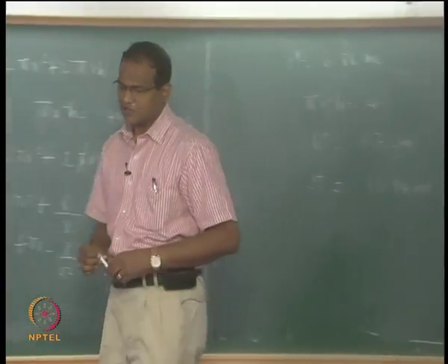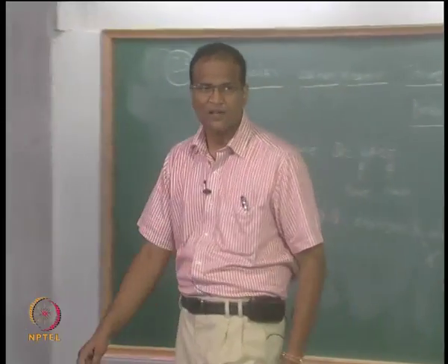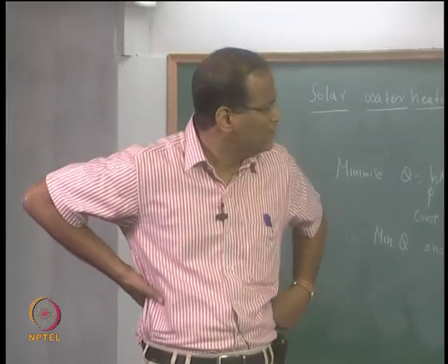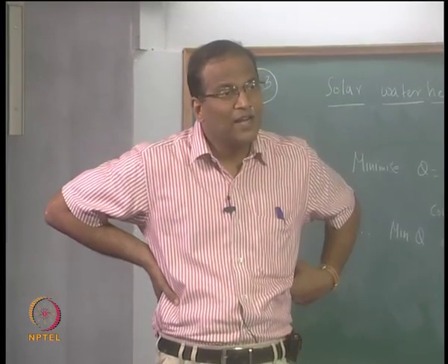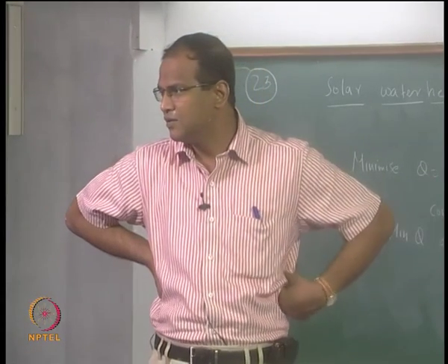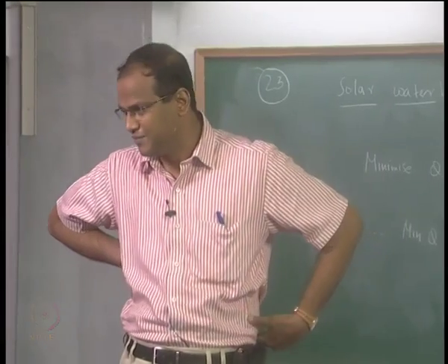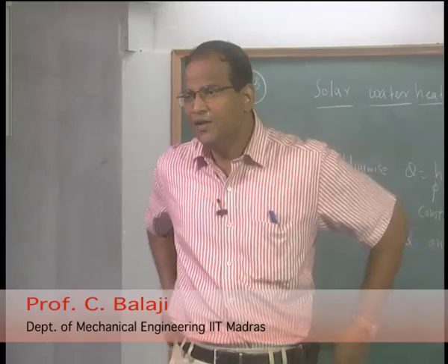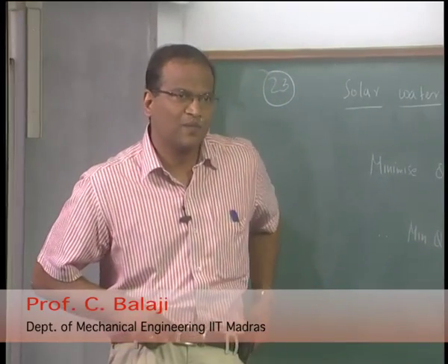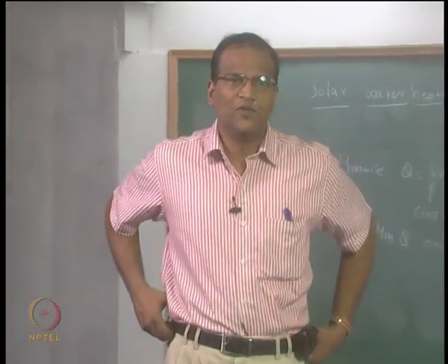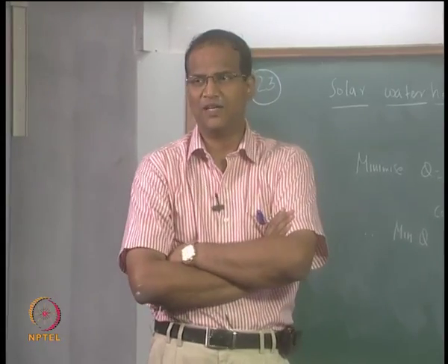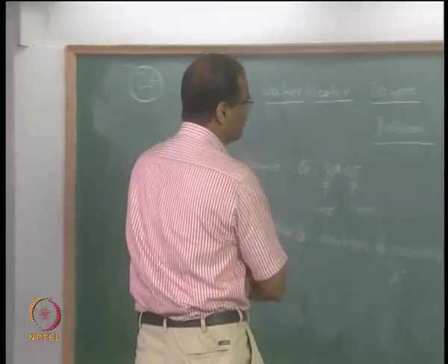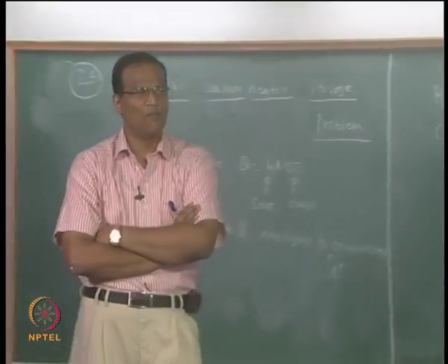So, if the temperature is constant, the convection coefficient is constant, the height of a cylindrical tank must be twice its radius. So it will be equal to the diameter, okay. All right. So, application of Lagrange multiplier method for a very practical problem. Is this clear? Any doubts?